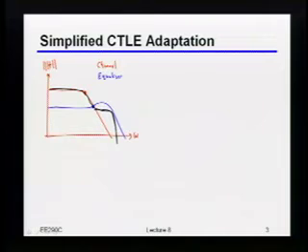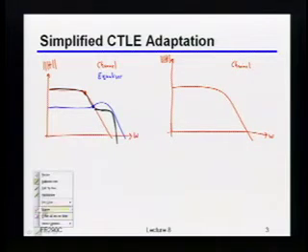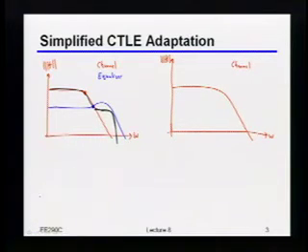So in other words, you're not equalizing enough, because clearly you've still got some low pass characteristic in that channel. Okay? So now what I want to do is repeat the same situation, but draw it under the condition that the equalizer is properly adapted. Again, I'm just going to do some magnitude behavior. This is again going to be my channel. And then in blue again, I'm going to do the equalizer, but this time I'm going to put it in the right spot.